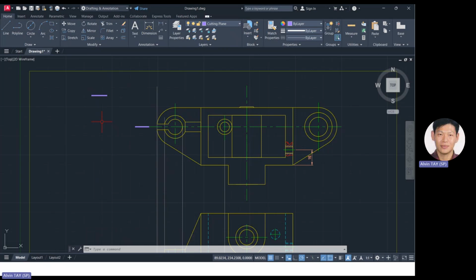Polyline button. The length is up to you. I'm not very comfortable with the length. Okay? Next, you draw your arrow. Quick leader, QL. Remember this. Q and L. Quick leader. Q leader. Okay. Enter.